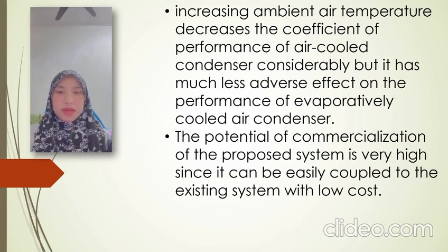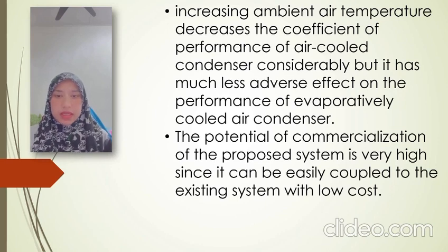The experimental test shows that the power consumption and performance of the evaporatively cooled air condenser improve significantly compared to the air-cooled condenser, and the improvement increases as ambient temperature increases. It was found that increasing ambient air temperature decreases the coefficient of performance of the air-cooled condenser considerably, but it has a much less adverse effect on the performance of the evaporatively cooled air condenser.